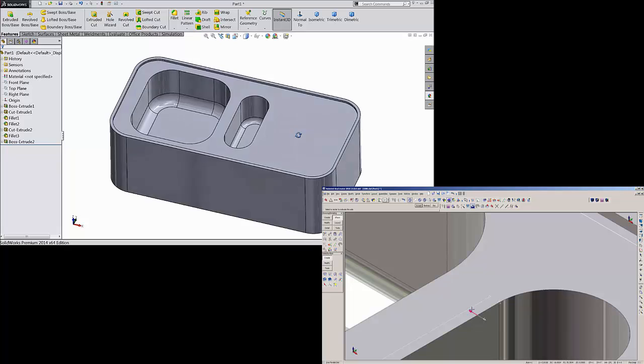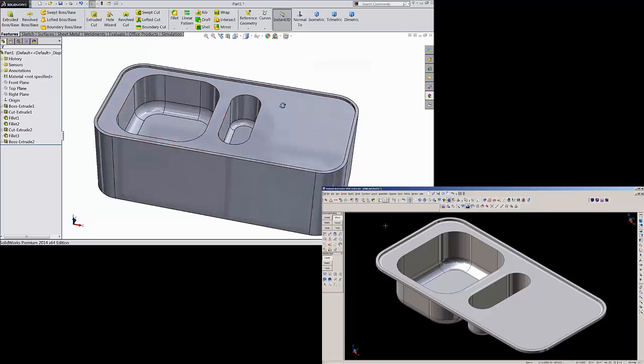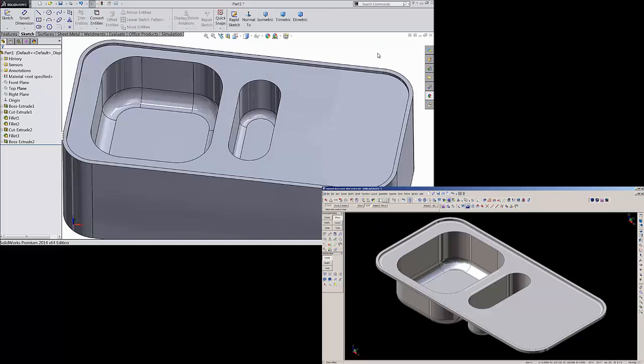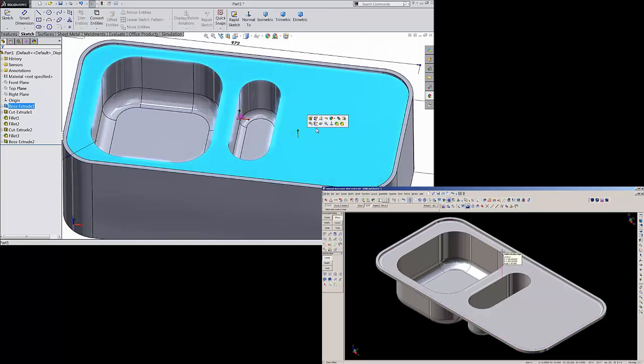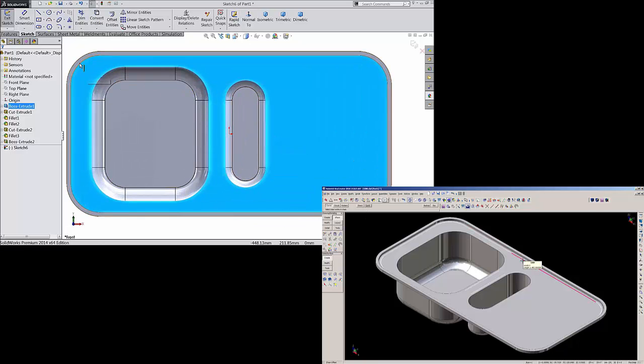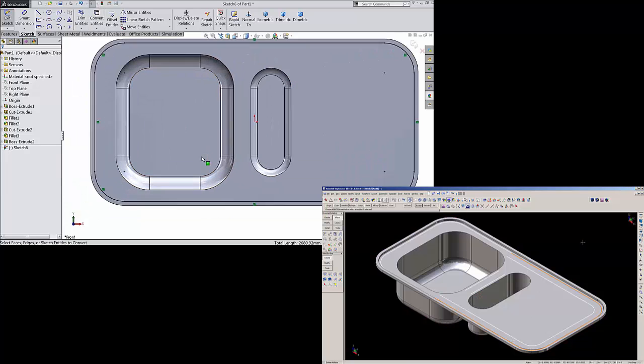Now a structure or a body is ready. Look at here. Keep perspective so it looks real 3D. Now select this face, sketch, select normal. This is the front face of this face. Now we will do one thing, the same thing, select all the edges, select here convert entity. Now it is converted.